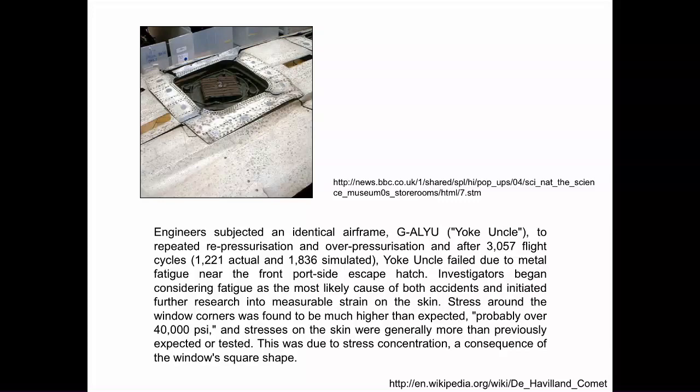Sometimes you wonder why. And why do I say square, not circular? What happens if you've got sharp corners? You get stress concentration as well. So it's quite interesting. Now because something like this happened, we learn from it, and we will not do something that will jeopardize safety. So if you get into a plane that's got square sharp windows, maybe you should be a bit worried. Now, this is how important it is